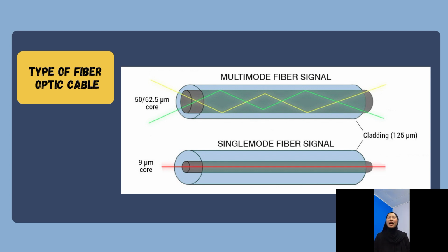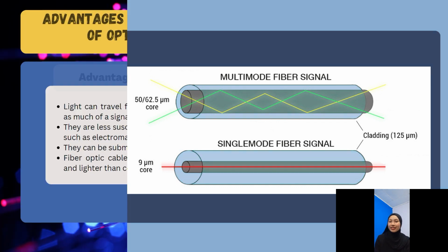Multi-mode fiber is the other type of fiber optic cable. It is about 10 times larger than a single mode cable. The light beams can travel through the core by following a variety of different paths, or in multiple different modes. This cable type can only send data over short distances. Therefore, they are used, among other applications, for interconnecting computer networks.